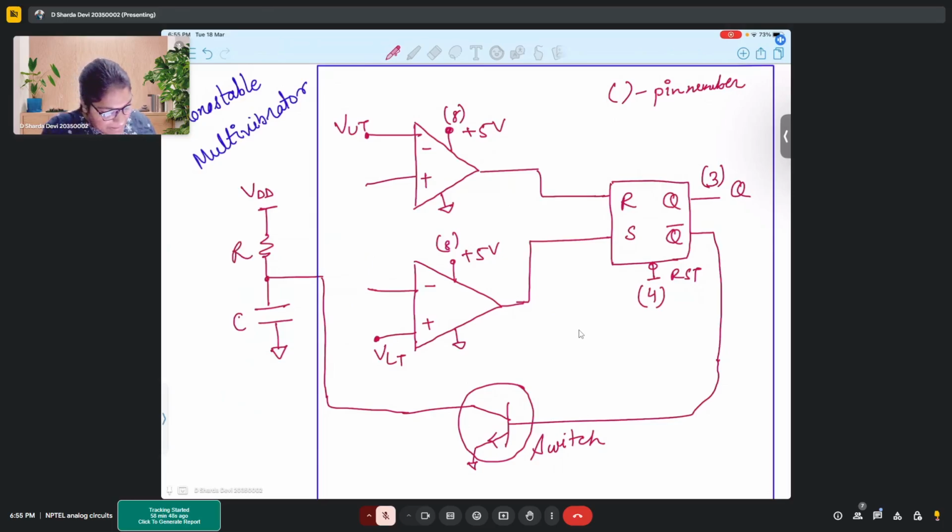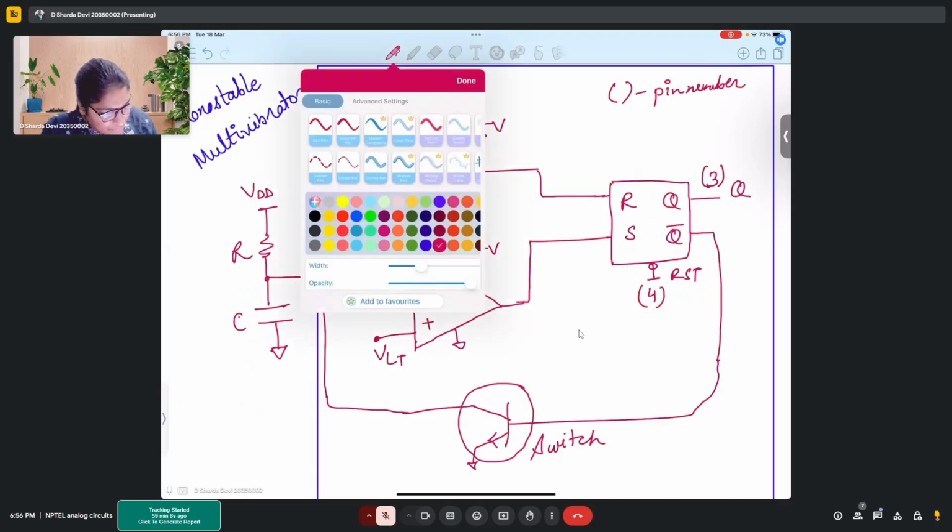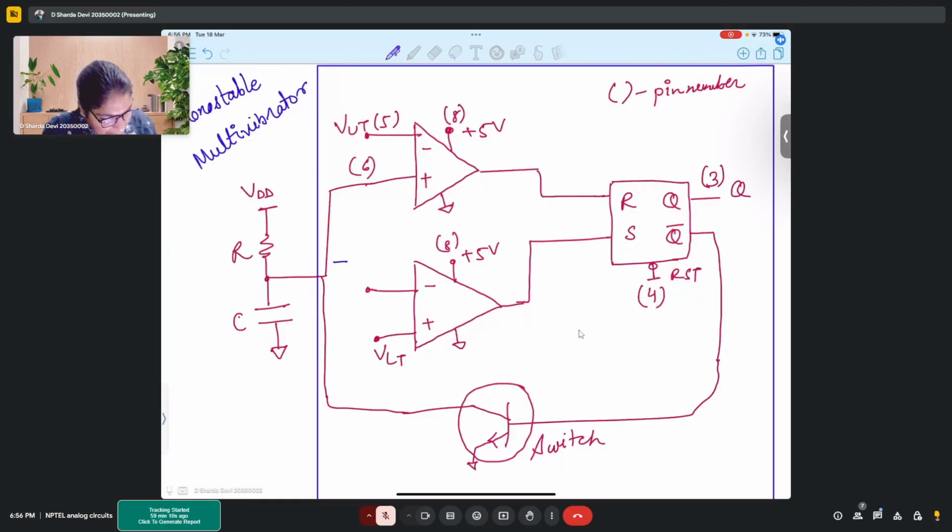One resistor followed by a capacitor. This particular position only connects to this. So this is pin number 5. This is pin number 6. And at this node is what you provide a pulse signal, which is actually a trigger, a small disturbance.